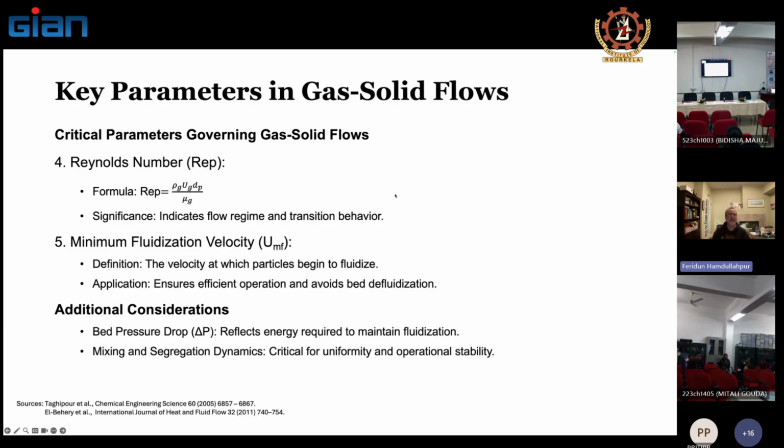We need to define a Reynolds number because it will help us understand the flow regime in which we want to be. And in this case, please remember which Reynolds number we're talking about. I am assuming you know what Reynolds number is. Its definition is given here. In writing Reynolds number, we always use a characteristic length.